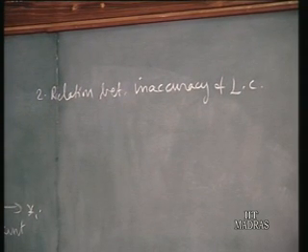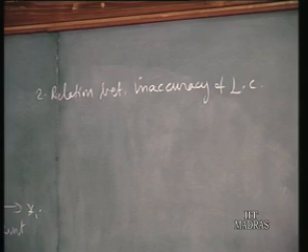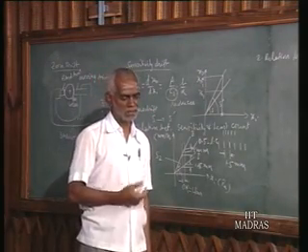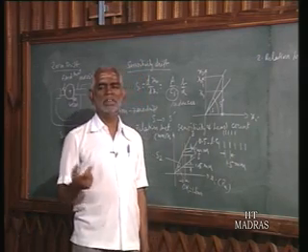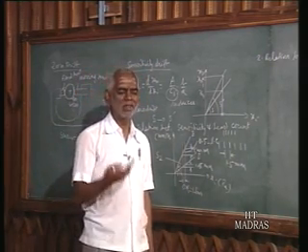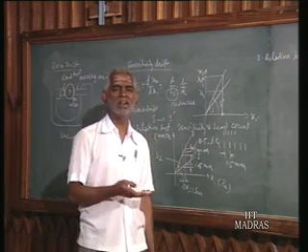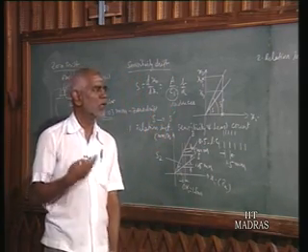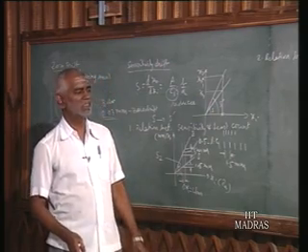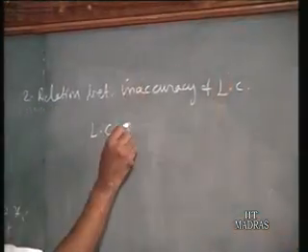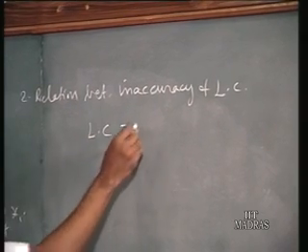Now, the manufacturer is supposed to give us the pamphlet for any instrument we purchase, and in the course of a number of years we have misplaced the pamphlet. What should we do? We don't have the pamphlet where we can refer to the inaccuracy or nonlinearity of the instrument. That book has been lost. In such instances, what is recommended is to make the least count of the instrument equal to the inaccuracy.